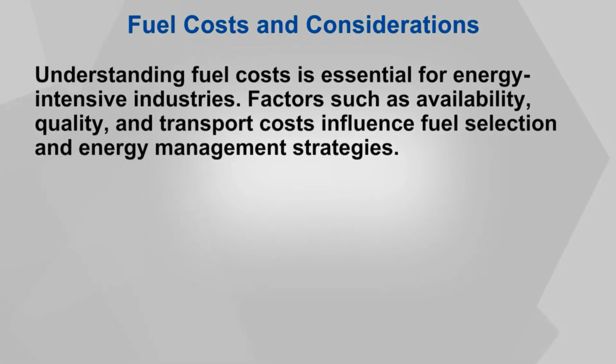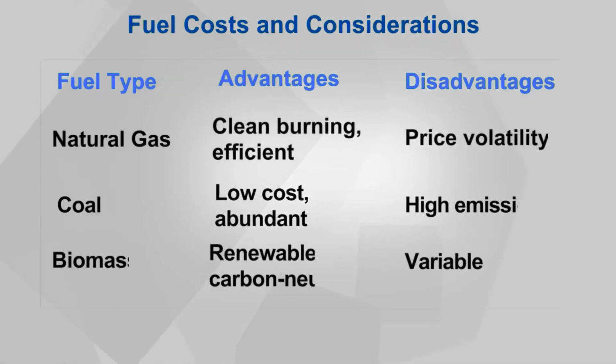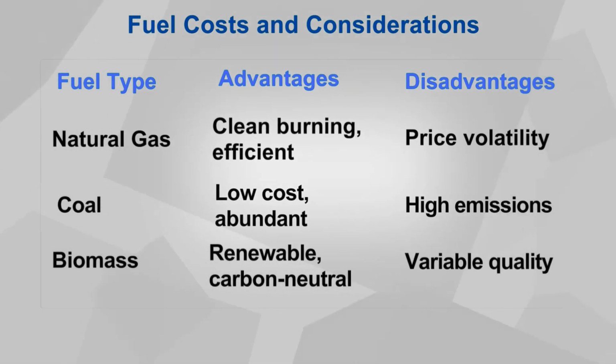From the perspective of fuel cost, a diverse array of fuels is available for thermal energy supply, including fuel oil, LSHS, LDO, LPG, coal, lignite, and wood. Understanding fuel cost involves considering several factors. When procuring fuels, consider the price at the source, transportation charges, and the type of transport. Quality is crucial as contamination and moisture can affect performance. Finally, assess the energy content or calorific value, which determines the fuel efficiency and cost effectiveness.